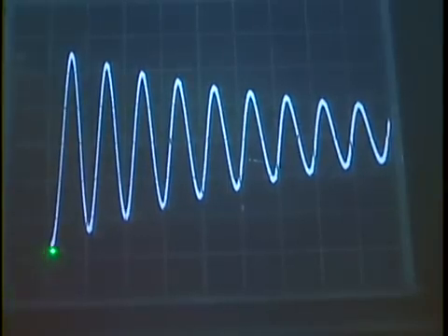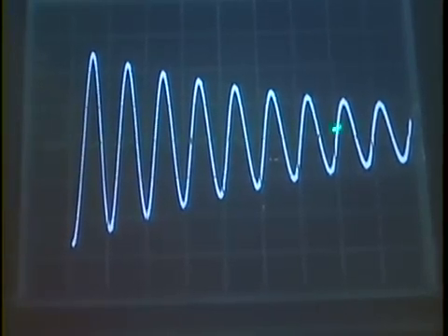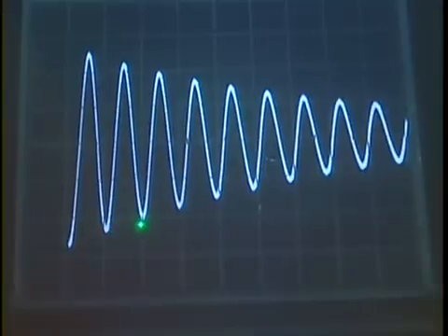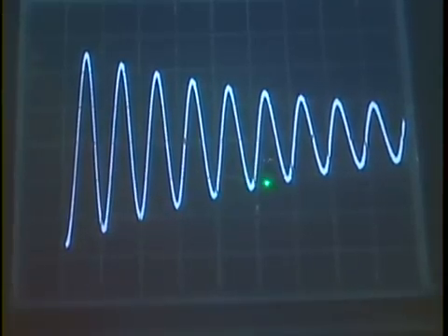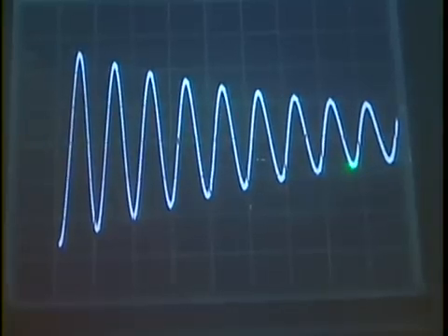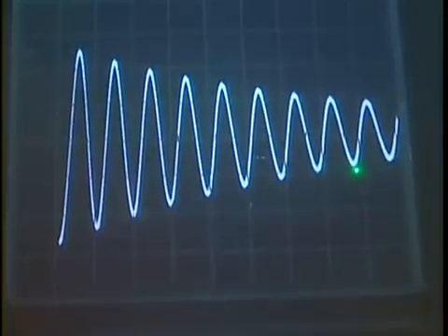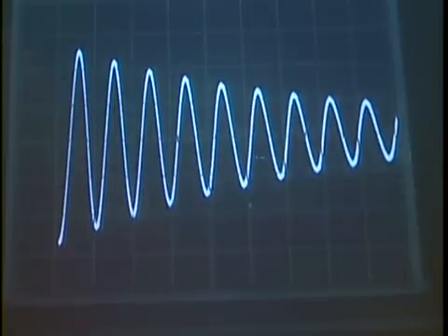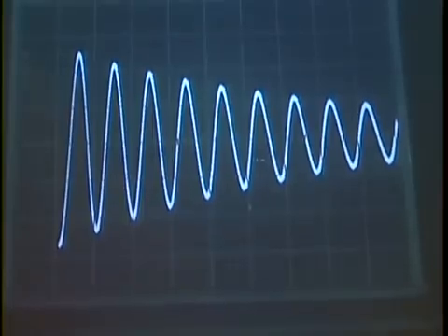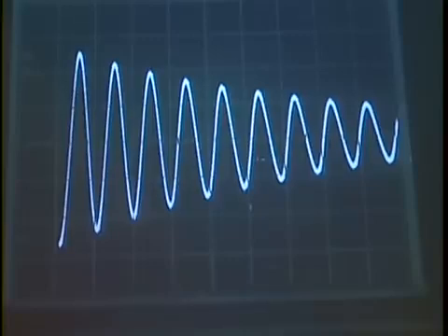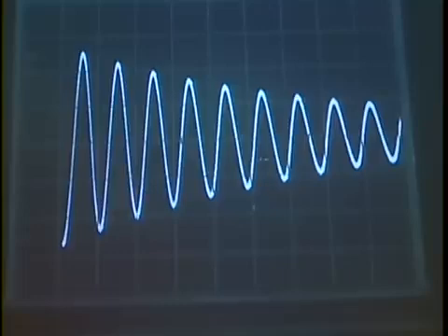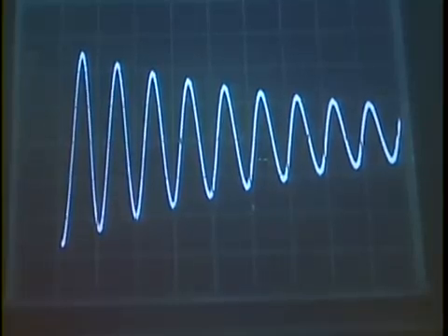So Q is 0 on the left side of the bottom. This is again fully charged, Q max. And now we go 1, 2, 3, 4, 5, 6, 7, 8. And the amplitude now is roughly the same as it was before when we had 6 oscillations. So you see that this works like a charm if you do this with an LRC circuit. Really quite remarkable. It's a dying oscillation, and the damping is the result of the resistor, which is dissipating energy.